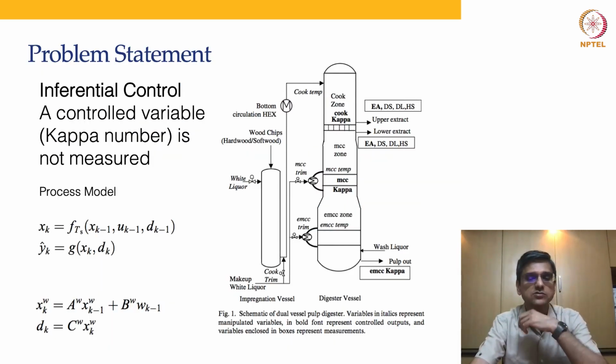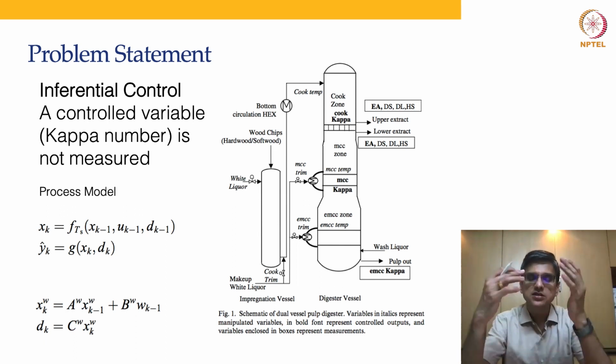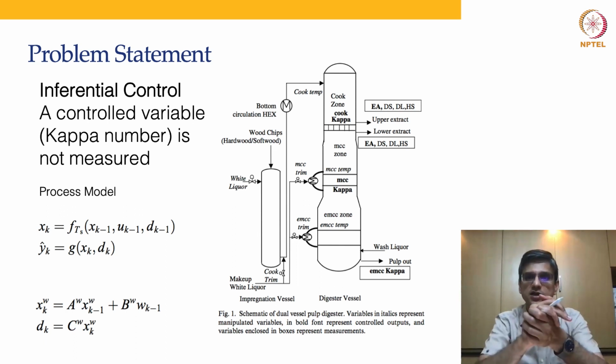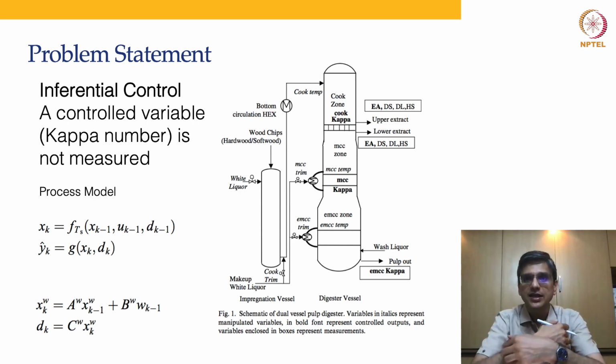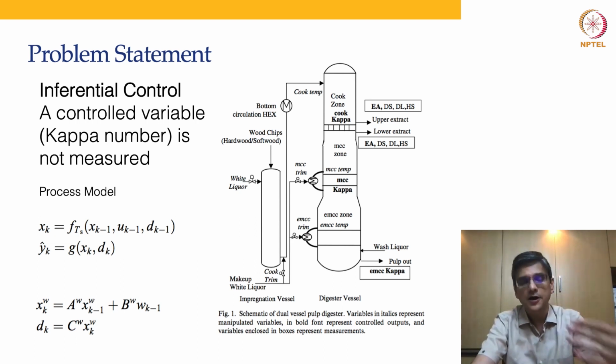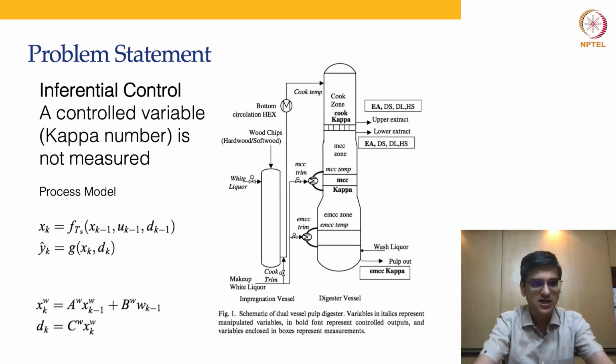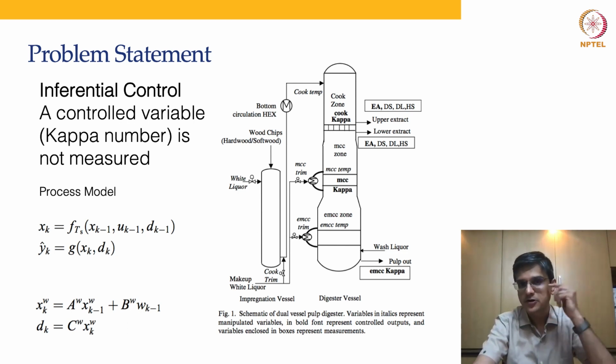Okay, now this is what is known as a pulp digester. What happens in a pulp digester is all the wood chips are sent into the digester along with a digesting material. Usually it's going to contain highly alkaline NaOH solution at very high temperature, and the alkali breaks down all the lignocellulosic biomass, and from the chips you eventually get the paper pulp. The paper pulp then goes through multiple steps of processing in order to get paper, whether it is cardboard paper or writing paper, doesn't matter.